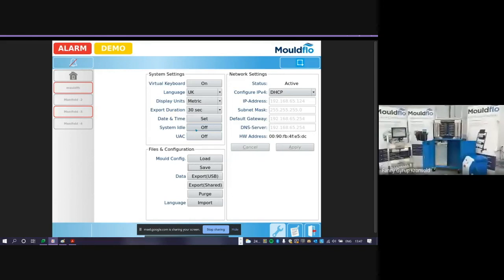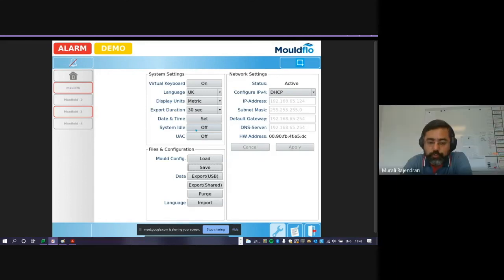And just to add on to this, the flow monitoring systems can come as a standalone unit where the 15-inch touchscreen is also part of the system. But the flow monitoring system can also be installed on the machine and then integrated into the machine control panel through a VNC connection or through OPC UA, correct? That's true. So we have a couple of integration options.